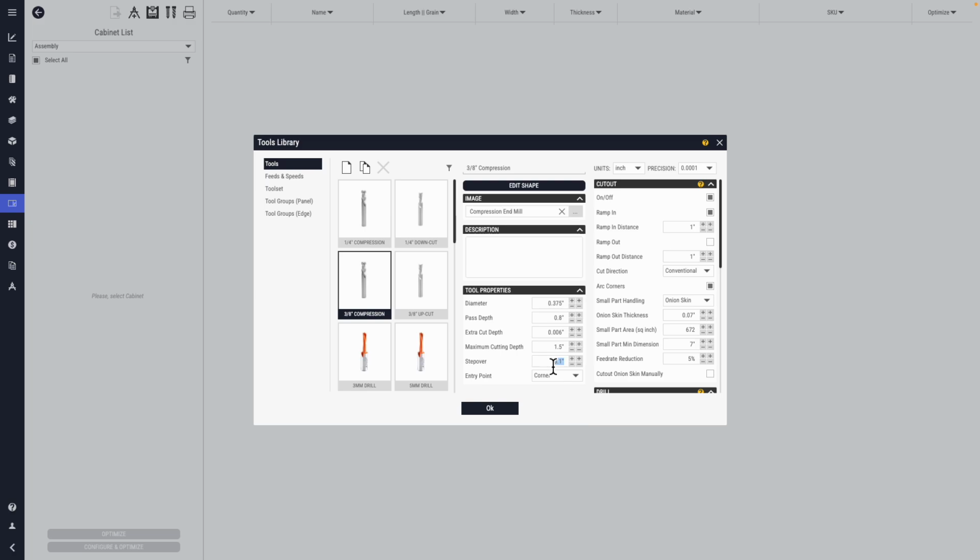Between each step, you will be sharing some amount of grass to make sure that there's no thin strip of grass left over at the end of the job. And the same deals with the pocket operations in the CNC. The step over is the amount of material shared between each pass to ensure there are no strands of material left over. You should keep this at a minimum so that the cut gets executed as fast as possible, but still with some guarantee of its functionality.